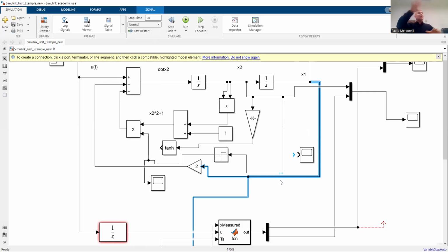If the spring is not linear, we have to approximate its characteristics. It could be that, when the spring is really compressed, I can imagine that the force as a function of the position is not linear. I cannot compress linearly when I am in the final part of the compression. This could also be considered, for instance, in a polynomial approximation. Basically, our system consists of a spring.